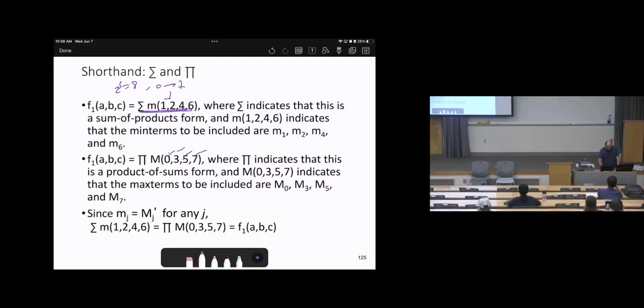Then we can add all of this. If we add all of this together, you will get it from 0 to 7. That's the range if we have 3 variables. How about if we have 4 variables, 2 power 4, then it's just 16. Then the range is between 0 to 15. We have M0 up to M15. Then if we need to make some indications, keep in mind, you need to compare between 0 to 15. How about if we have 2 variables, 2 power 2, which will be 4, then we have from 0 to 3. Okay? Then look between these ranges.